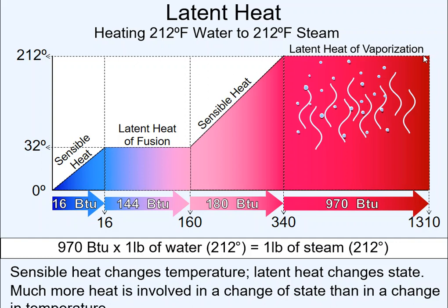So as it climbs down and it goes across, it's going to hit the saturation point and it's going to cool down. It's rejecting heat and it's going to cool. That's going to allow it to go from a vapor back to a liquid until it becomes 100% liquid. So you could imagine if you had a pot of water on the stove and you could heat it up to the point that all the water boiled away, and then somehow magically you were able to capture all that steam and cool it down. Well, in essence, all the water would come back once you cooled it down, because it's just going to change states back the other way. Now, obviously, that's not going to happen, but in theory, that's what would happen.